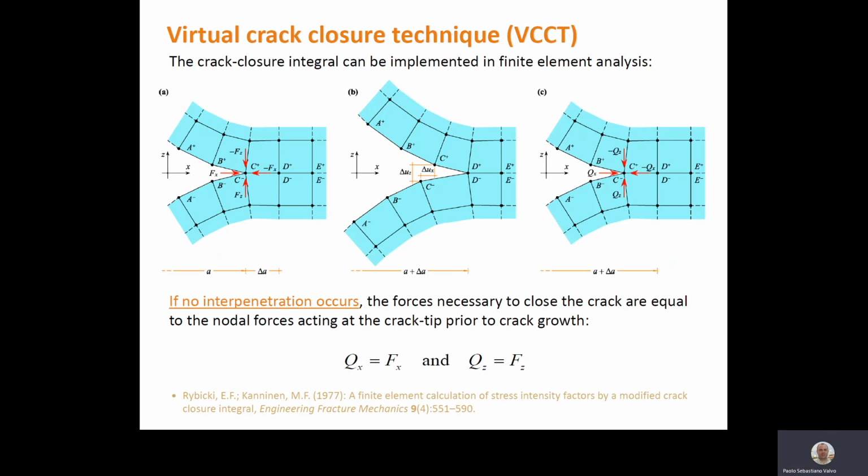The same concepts can be implemented within a finite element environment. In this case, Irwin's crack closure integral becomes the so-called virtual crack closure technique. Figure A shows a part of the finite element mesh. We consider a plane elasticity problem. We are in the neighborhood of the crack tip C, and the crack has an initial length A.